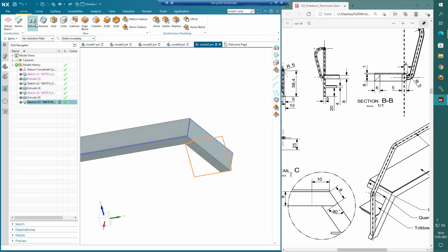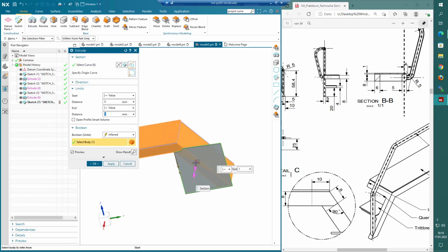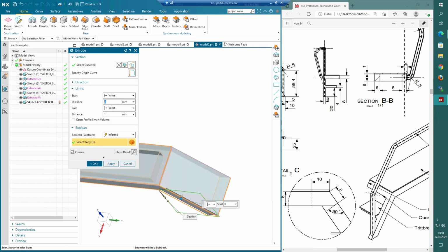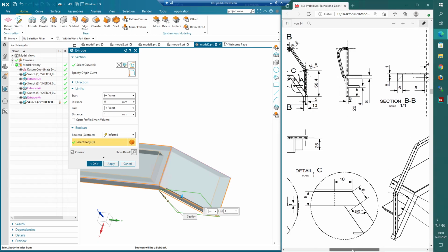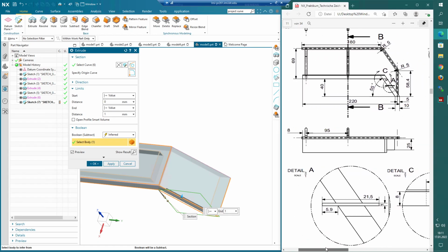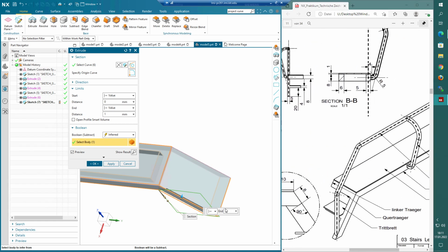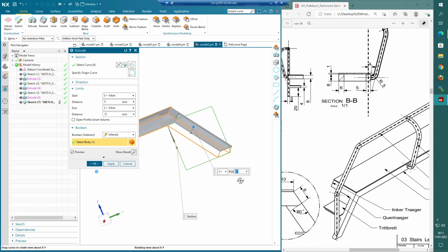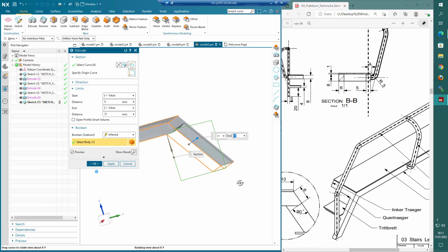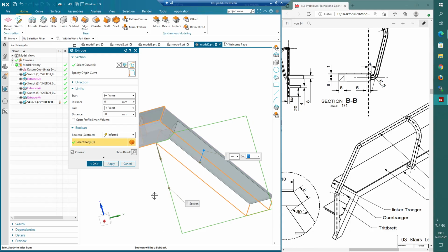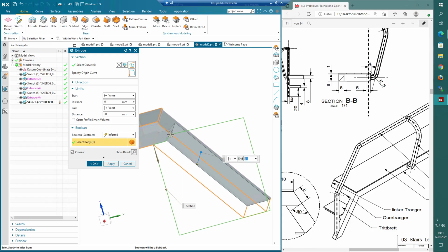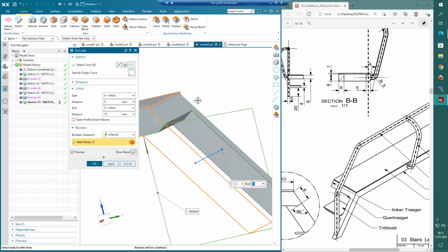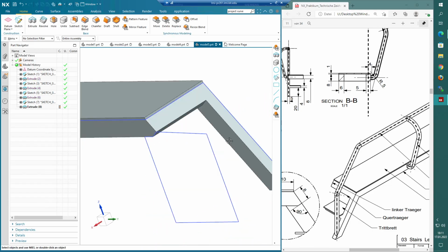And now we can use extrude in the other direction, and we need to leave 5 in the end, we have learned. And how is our current width? It was 36, if I'm remembering correctly. So let's see how 31 looks. I guess that looks good. And you can see how the rest around here doesn't matter, obviously. But here we have this little detail. And if I click on OK, we select that.